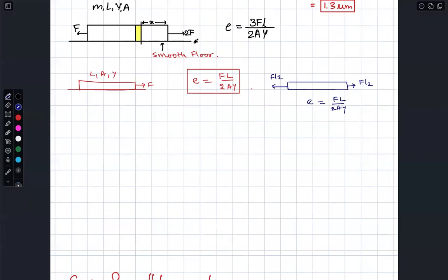Similarly, now you see here, total force is 3F. I mean, add all the forces. Remember, not net. What I have done here, F by 2 plus F by 2 is F. F plus 2F is 3F. Remember, this technique is applicable only under one condition. What is that? The forces must be applied only along the ends.